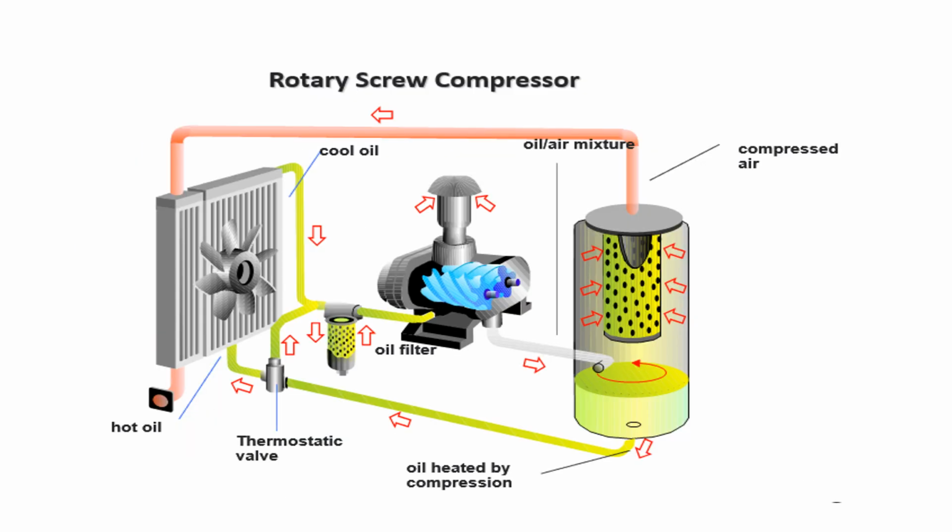So this is a typical lubricated screw compressor. Here you can see that after compression, the air and oil mixture goes into the separator. Oil is separated over here, and the air after separation goes to the air cooler and then out of the air compressor for drying application. And after drying, it is pumped to the compressed air network. So after this, there's a dryer and the network.